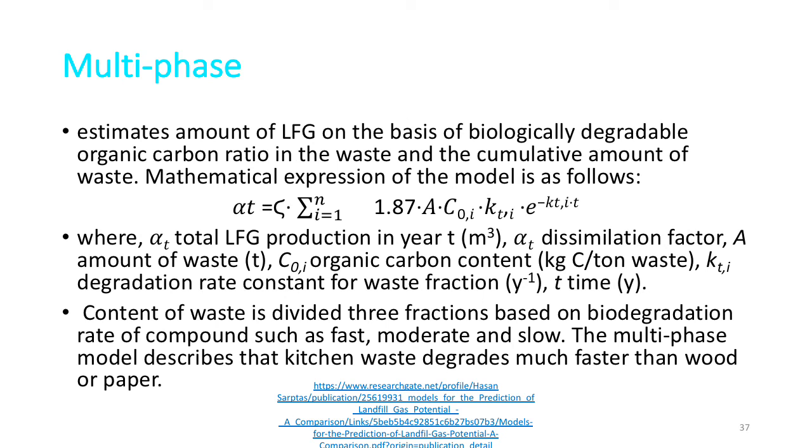The third model is the multi-phase model, in which the LFG is estimated on the basis of biologically degradable organic carbon ratio in the waste and the cumulative amount of waste. This is the mathematical expression given, where alpha T is the total LFG production in the year T, alpha T is the dissimilation factor, A is the amount of waste, C naught is the organic carbon content, KT is the degradation rate constant for the waste fraction, and T is the time.